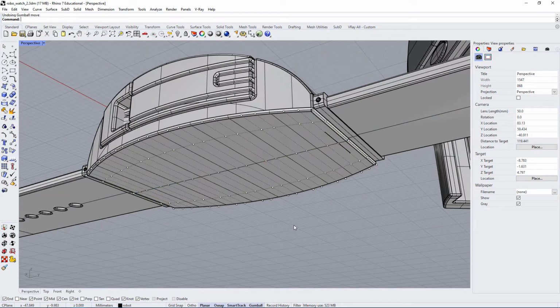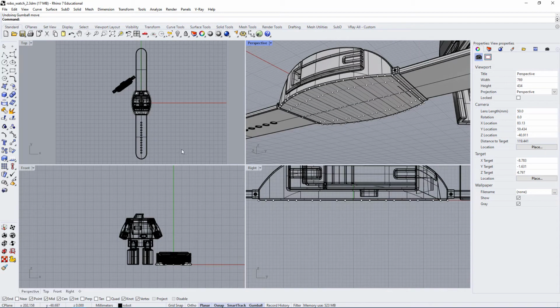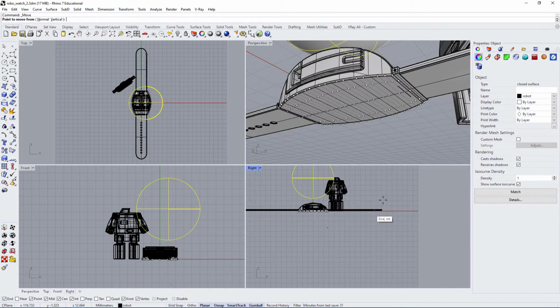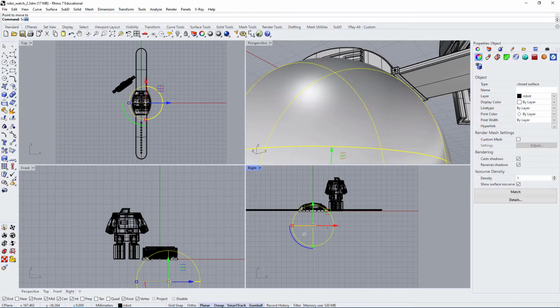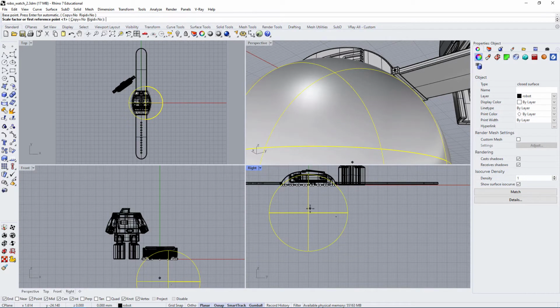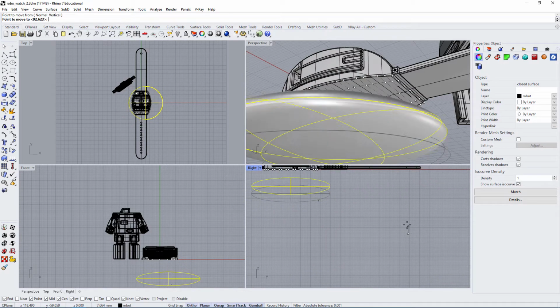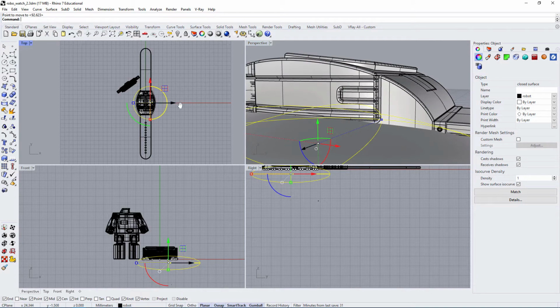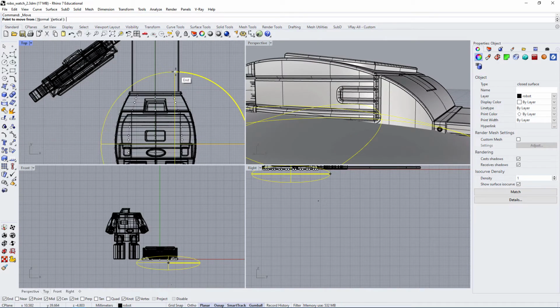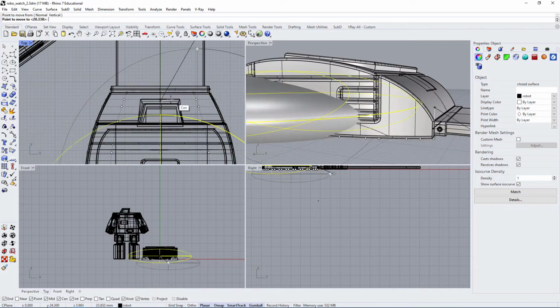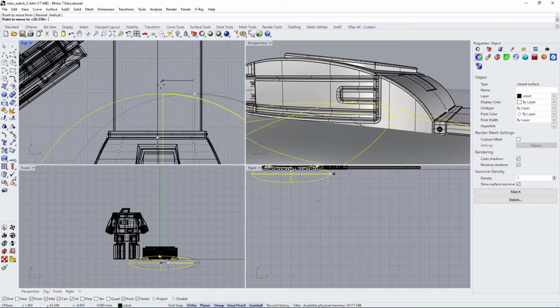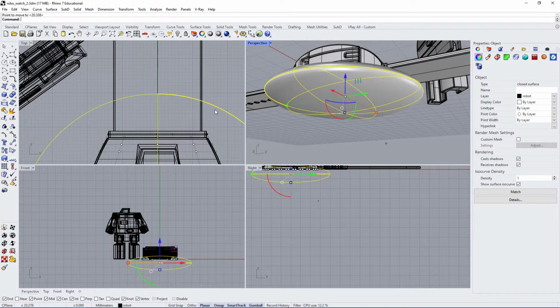Now, what you shouldn't do, and I've seen a lot of people do this in the past, is go in and use something like a primitive, something like a sphere. If you use a sphere and you intersect this, you can very quickly get a concave or a convex surface. I see a lot of people do this. And usually you get some really strange stuff happening once you get to your transitional surface, because transitional surfaces don't usually like primitives like the sphere.